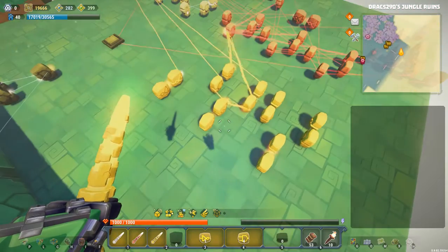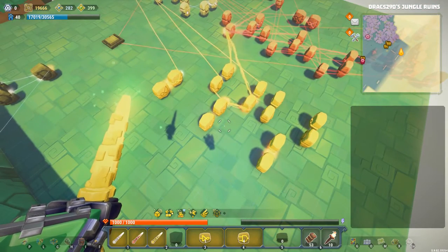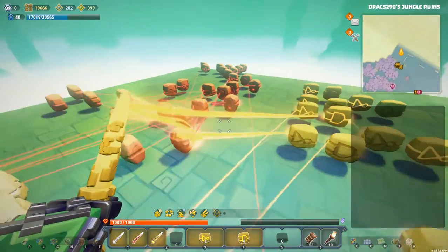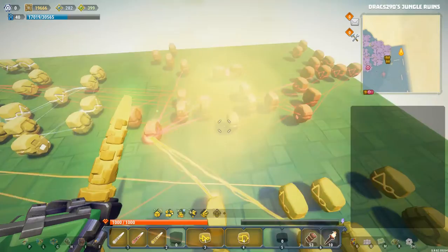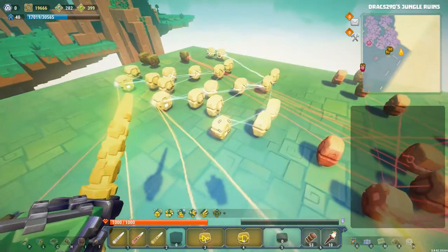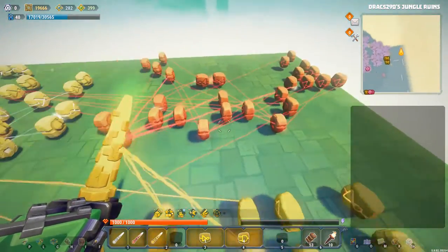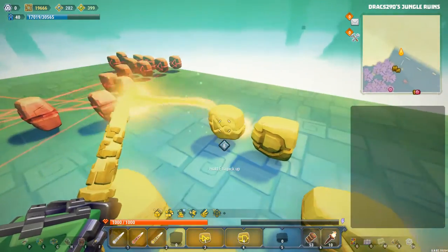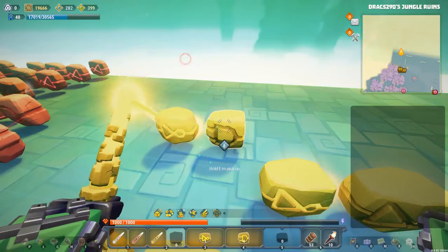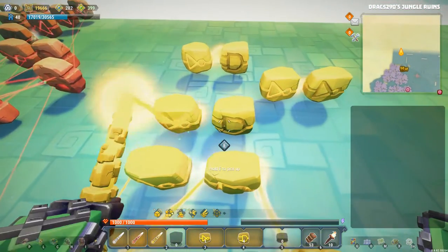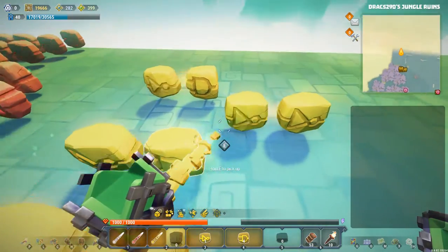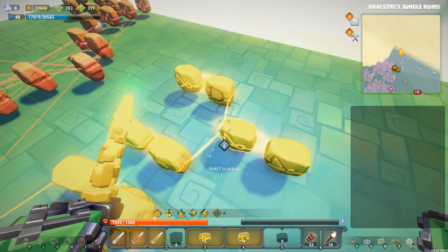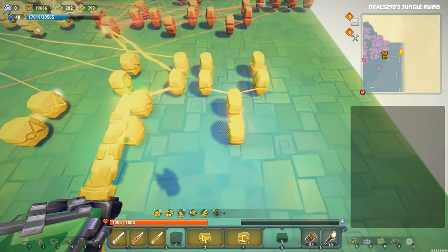Okay, so now that that is up and running, we want to do the same with this latch here, the third latch in the counter, and the second latch in the sequencer. Once again, the counter latch is going to be our A, and the sequencer latch is going to be our B. But first, of course, we need to hook these up to where they're supposed to be. So this NOT gate is going into the A up here, and this NOT gate is going into the B down there. Then these AND gates are going through into our node, just as before. So there we go, not a problem at all.